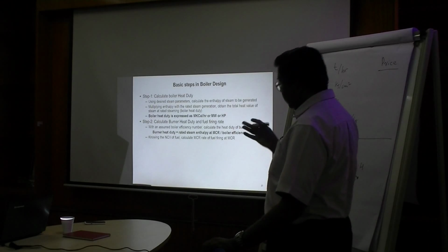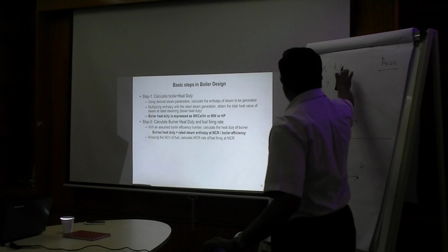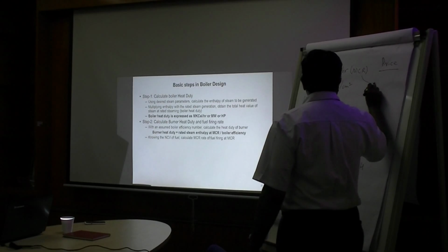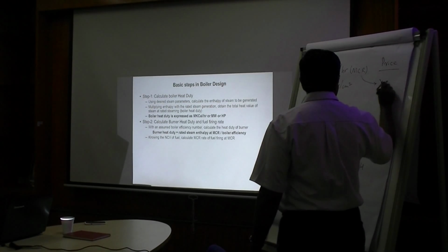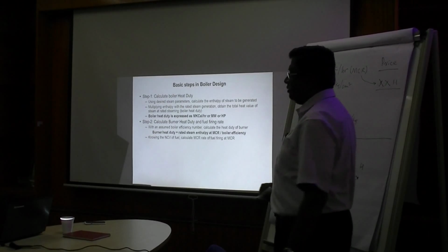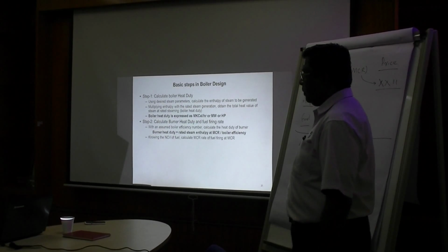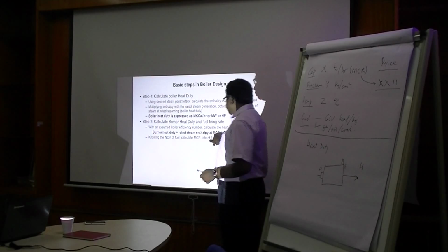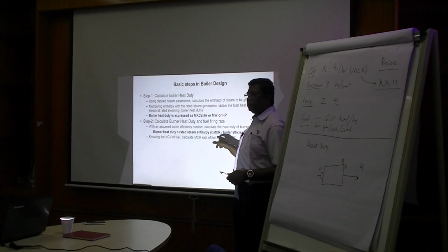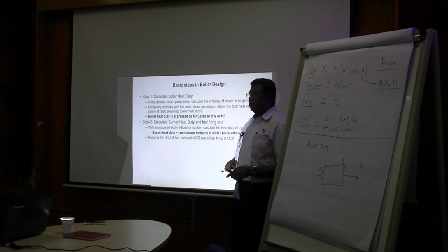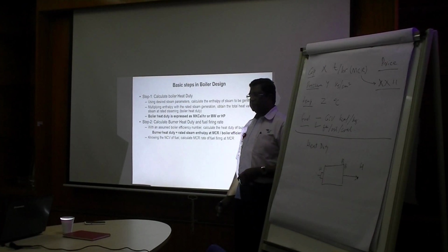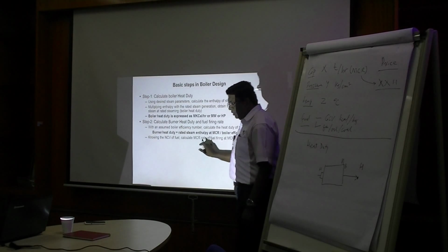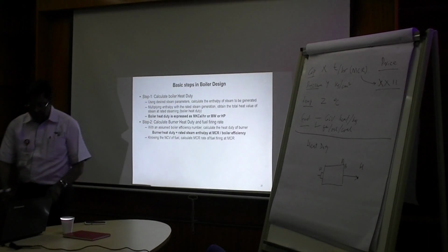Some people will do that. If they first take the peak number here, instead of saying X tons per hour as MCR, what they take is X tons times 1.1, if 10% is the peak load. And then everything goes up by 10%. That's okay. But this point must be fixed beforehand, before we start the actual design. Okay, so then you get to know the amount of fuel to be fired.